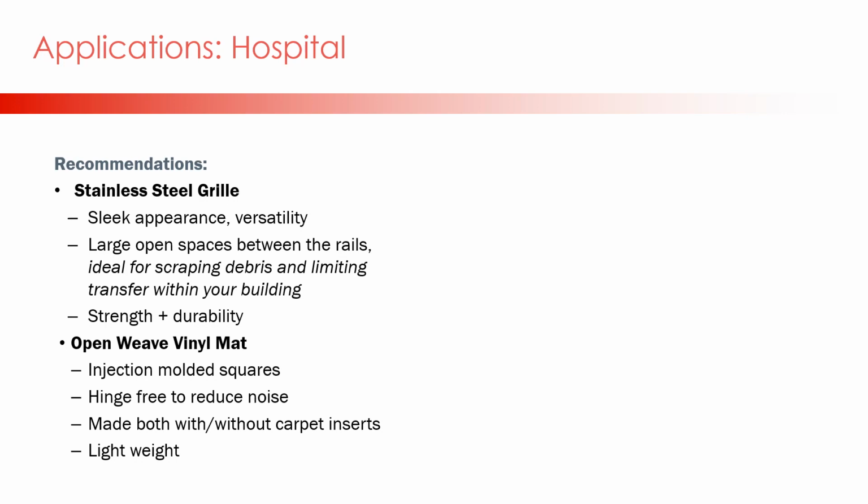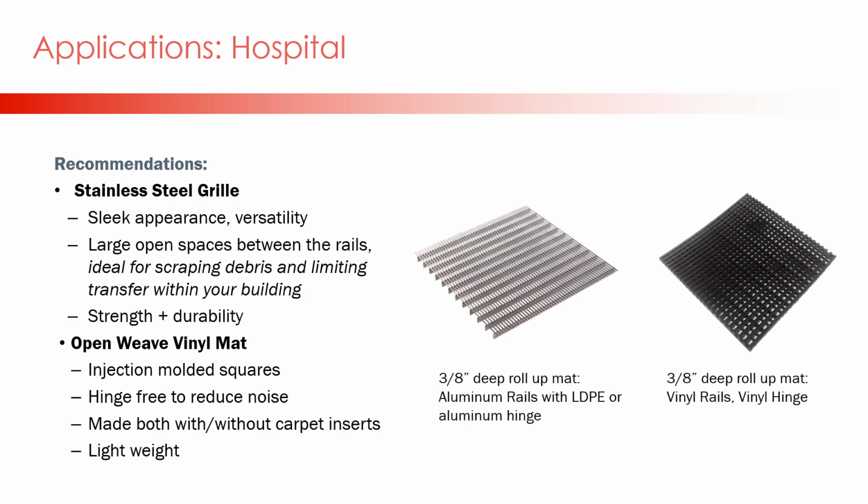We have 2 very different options, and the decision will be based on your aesthetic design requirements. The best option is stainless steel grilles. They provide a sleek appearance to give customers a positive first impression. You can choose products from 3/8 inch to 1 1/8 inch deep. The deeper well will accommodate the debris in between cleanings. One consideration will be cost. As you increase the depth, you are adding more material, so the cost will be higher.